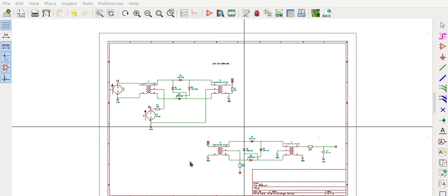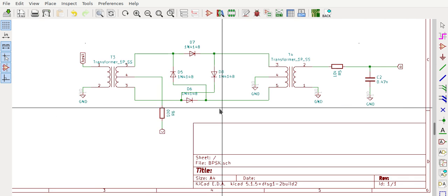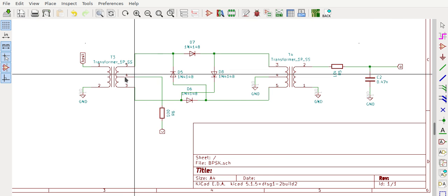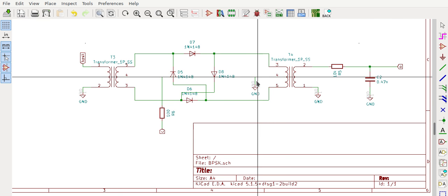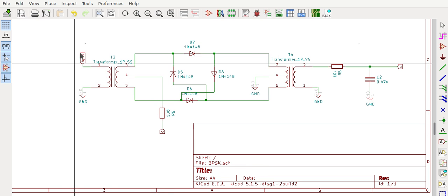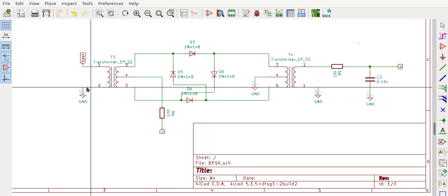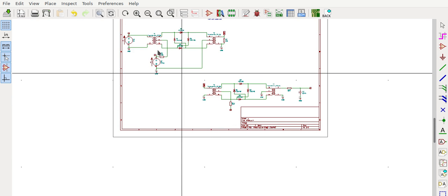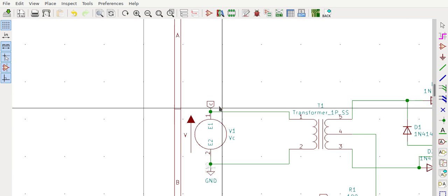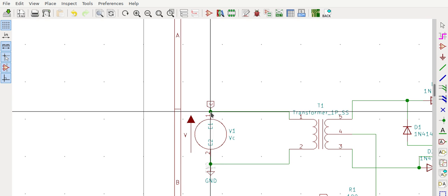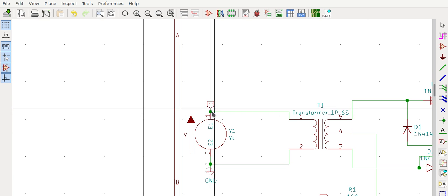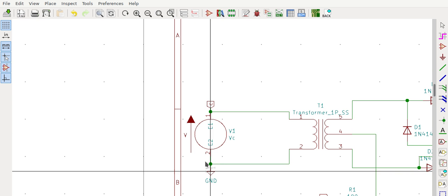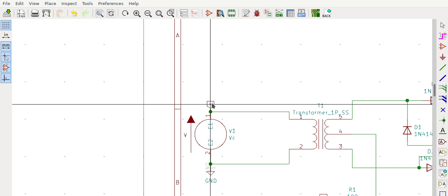So that approach is what I am using. I will be providing the carrier signal to these two ports, and I will be feeding the BPSK signal here itself. And the carrier I am taking using this label, and I have defined the label here as well. So this point where I get the 101 kilohertz sine wave, one point is grounded and the other point is connected to this label C.